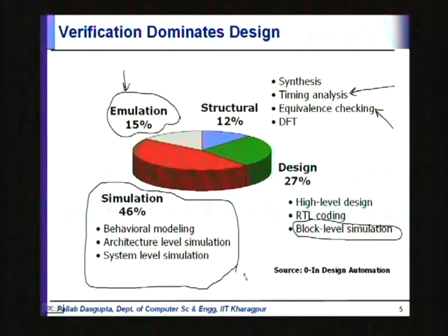So people are saying, why don't we get a first silicon out quickly and then do most of the verification on that first silicon? The advantage is that the silicon runs much faster than simulation. Simulation is running on a processor, and the silicon is going to run on its own clock speed, which is pretty high. So why can't we do the verification after taping out the first silicon?